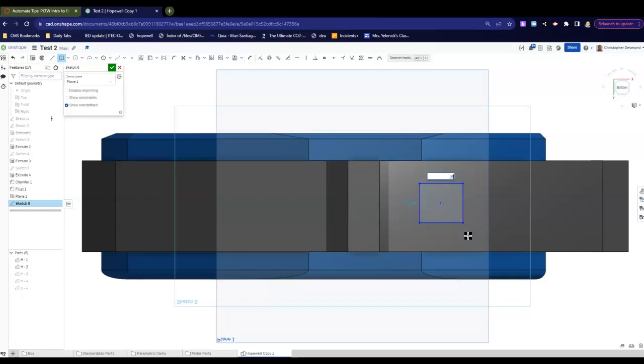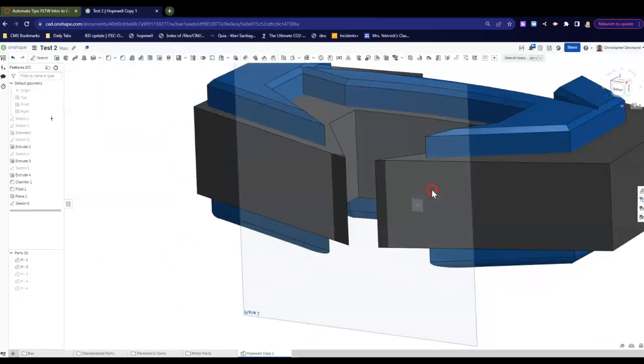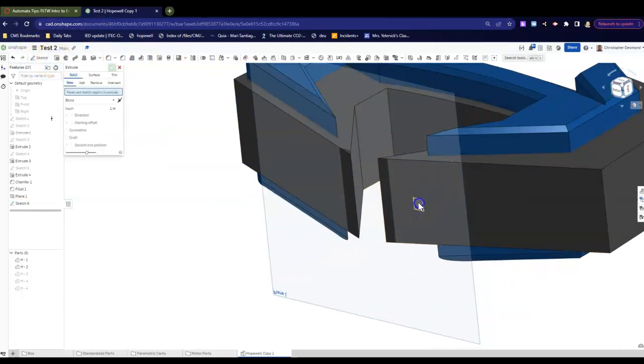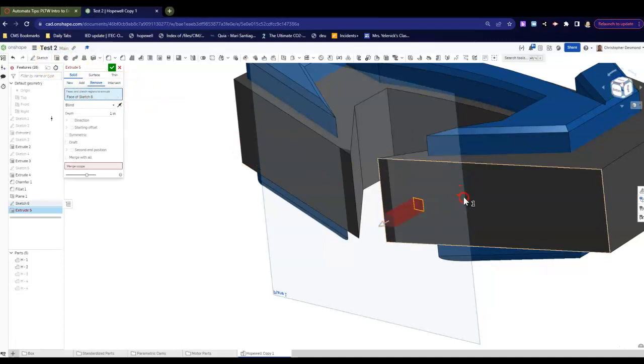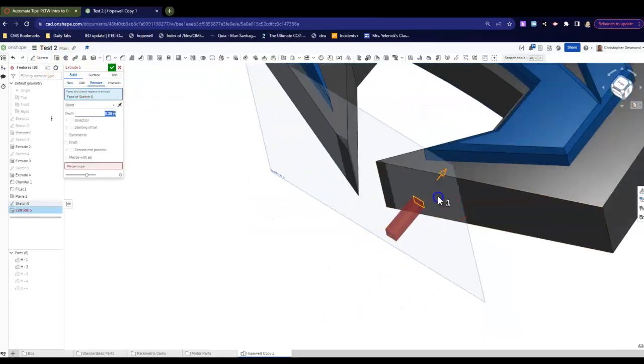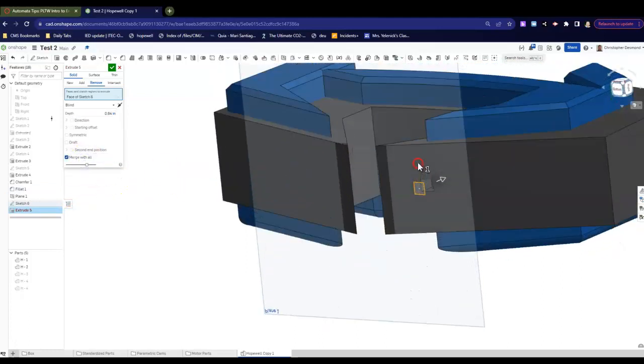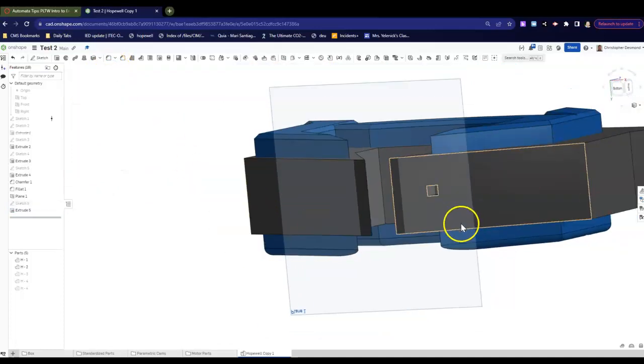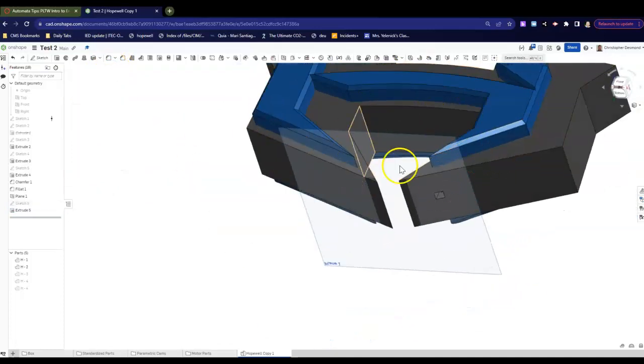The stick itself is 1/4 of an inch. So I'm going to make sure that I have some space and I'm going to do 0.27 by 0.27. So now I know that that's the size of my hole. I'll put it directly into the center. And now I am just going to remove that geometry so that the stick can cut out. If it doesn't show up, just click this merge with all, and then you will be able to connect whatever you've created. All right, so you already see that this is going to be very large in reference to my entire box, and that's okay.